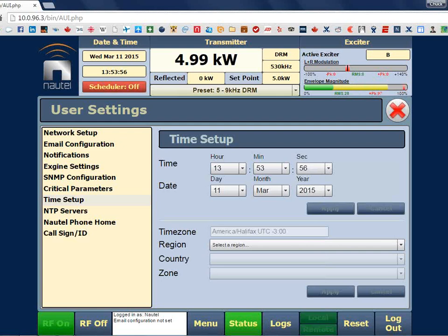Which power phase is the exciter connected to? That's a dandy question. The exciter is powered indirectly, I guess, through the low voltage power supplies, which are on the secondary of the transformer. So if you lose a phase on the transformer input, regardless of which phase you lost, would you still be able to run the LVPSs and thus the exciter and control? I'm not sure. That's a good question. All right, we'll find out and let you know, John.